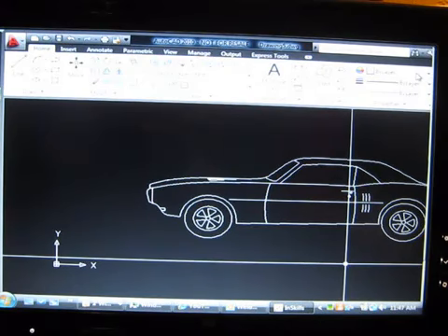If you want to get to the toolbars and the menu bar and get rid of the ribbon, that's fine. AutoCAD has a workspace called AutoCAD Classic. You can turn it on by switching workspaces. Your workspace is an interface screen in AutoCAD. It can be arranged in many different ways and for any reason you want it to. AutoCAD comes with 3 main workspaces out of the box: the 2D, the 3D, and the Classic.